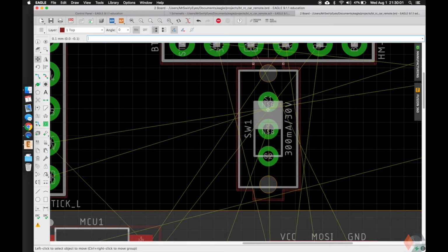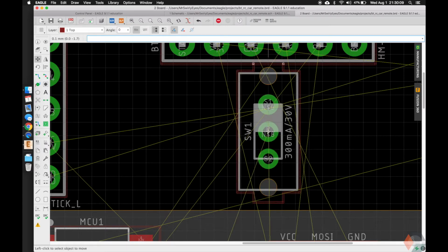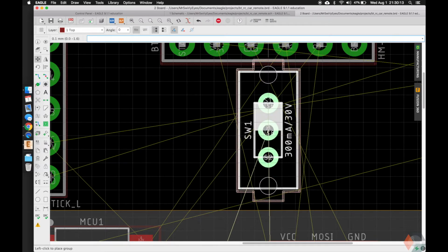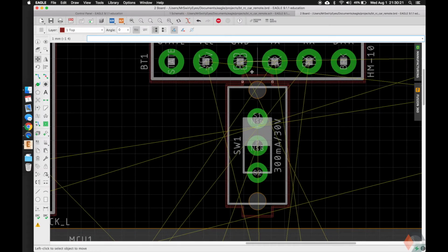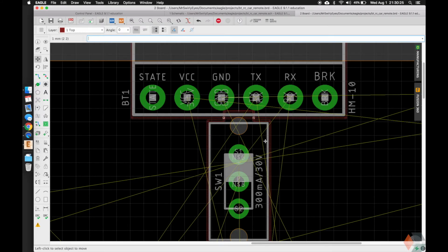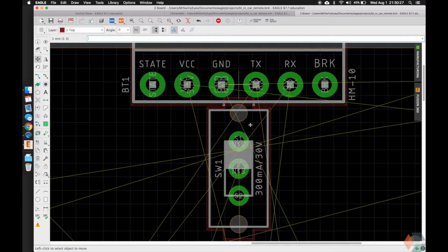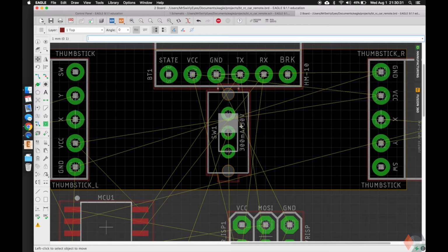So when I normally design things, I don't want the T keep out that I have here to go through this right here. In this case, I have it go through a little bit on my original design. If you decide to use this in a different project, getting too close to this may affect you. But since I've made this and printed it out and I know how it'll appear, I'm going to bend the rules a little bit, but I encourage that you do not until you're more comfortable designing boards.